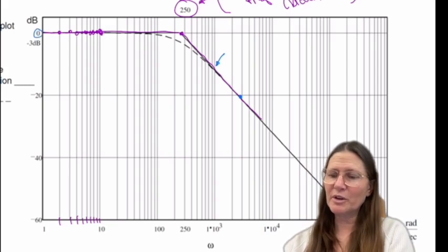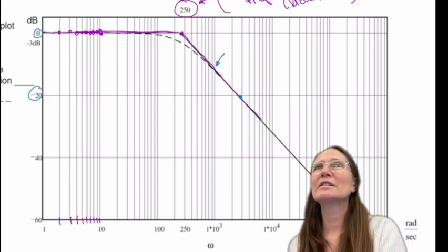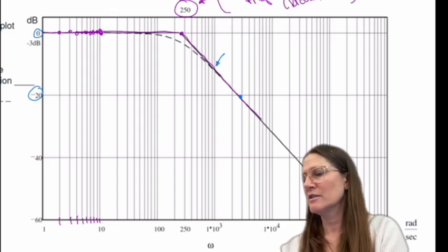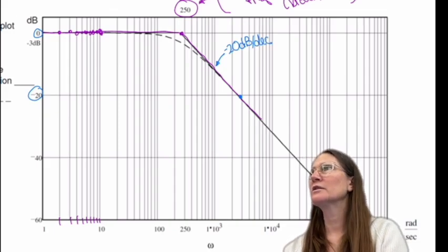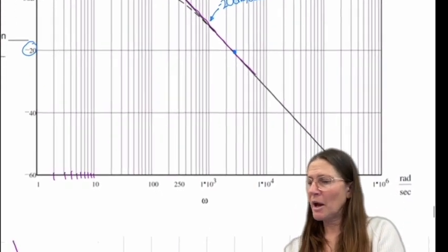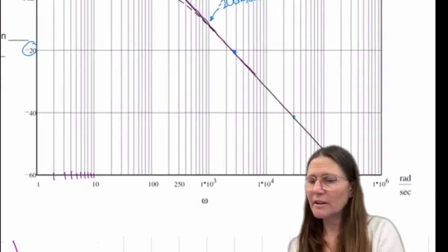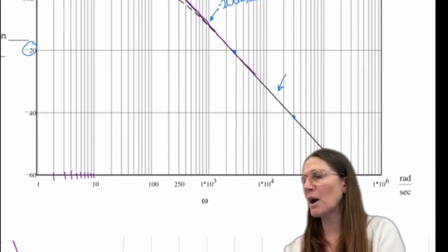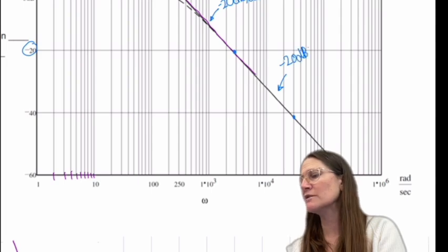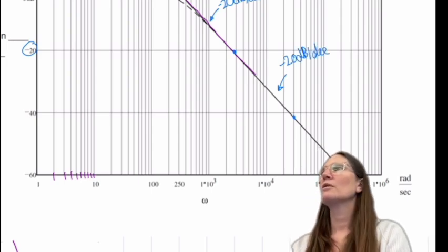So it goes from 0 to about minus 20. So approximately minus 20 dB over 1 decade, right? What about going one more? It's almost about the same. It looks like that slope is continuous at about a minus 20 dB per decade slope. Okay?